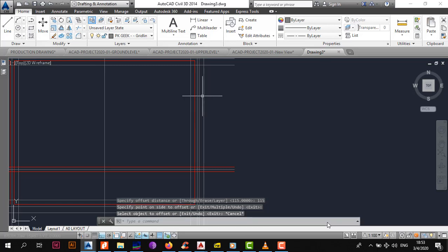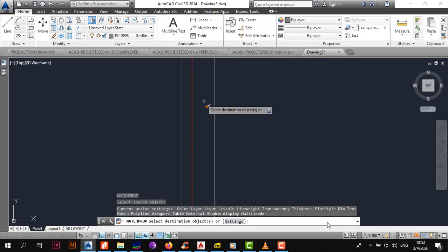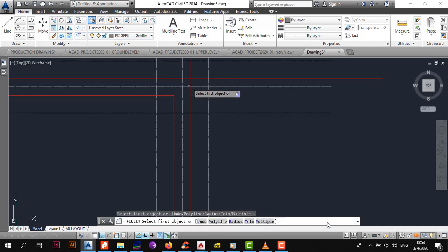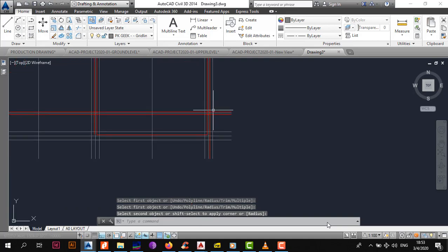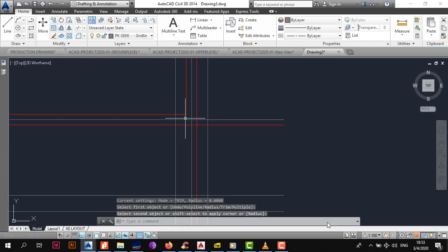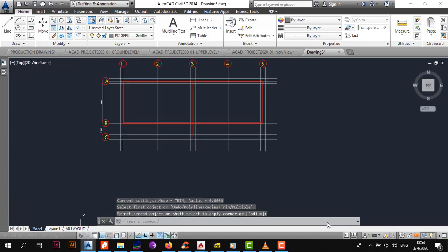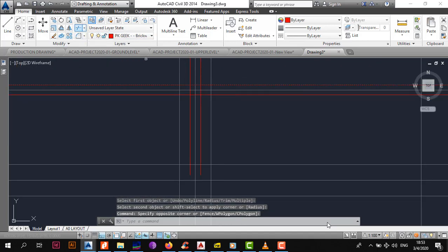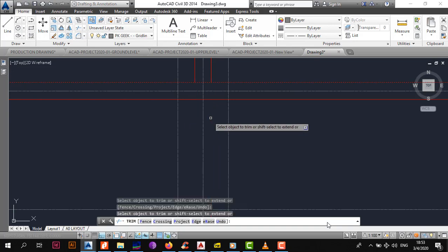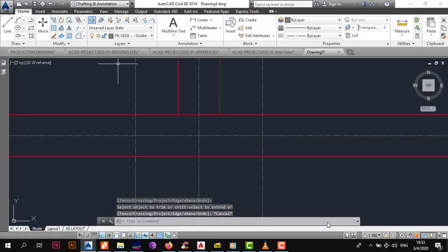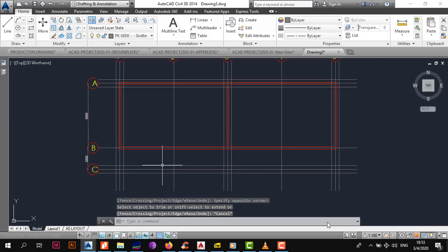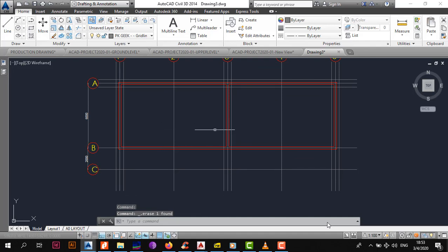And we offset this by 115. You know, mistakes happen, and this shows you I am human as well. Making mistakes do happen, bro. So let's just make sure we do it properly though, because that's the point. You want to do it properly, and there you go, your lines are good to go. And then just trim everything else that is not necessary. Right, just repeat trim. We got our walls up, so this is the correct setup for our walls.